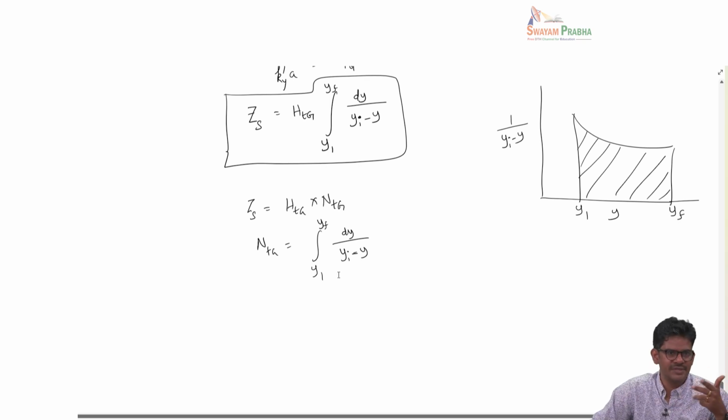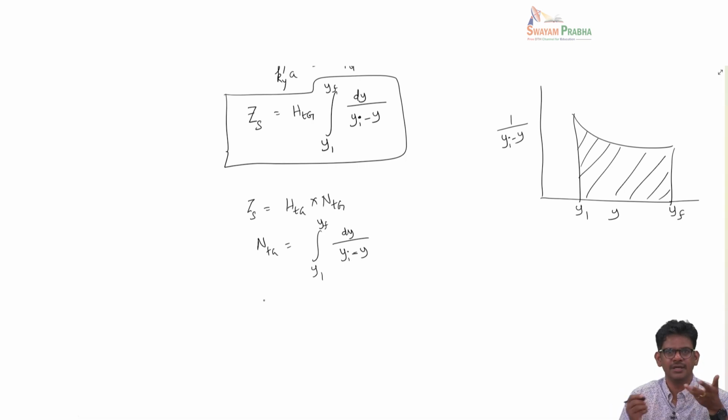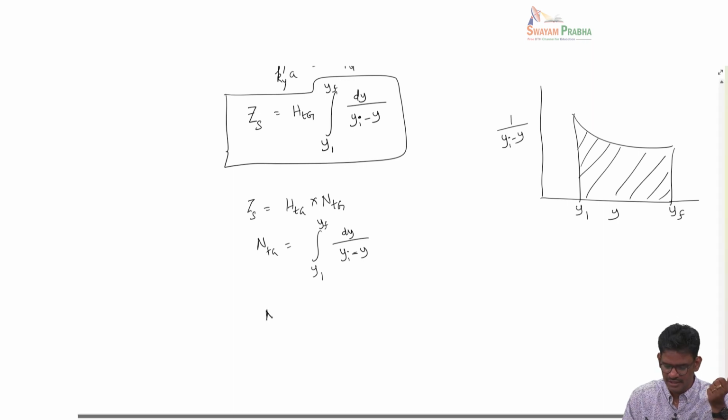In some of the problems I solved in the class, I think batch distillation, we had a similar kind of integral, and we approximated the equilibrium line to a straight line for a very narrow range of concentrations. If you do continuous vacuum distillation in those ranges, we can approximate the equilibrium line as a straight line. So in those cases, it makes sense to define the overall NTOG.